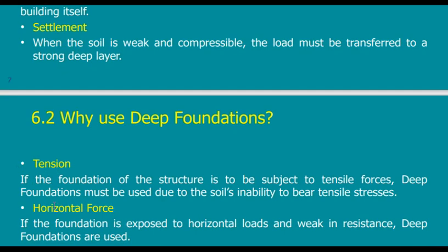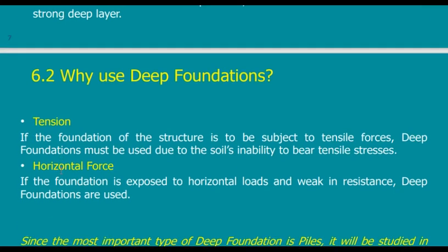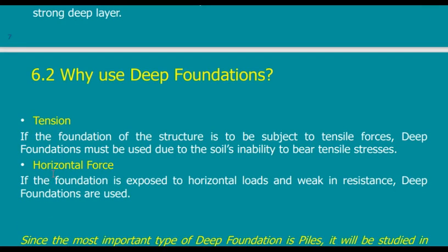If I have tension, shallow foundation is not possible, because shallow foundation can carry vertical load. But if you have tension, then the tension will lift your foundation above the ground. So you should use piles or deep foundation. Or you have horizontal load.